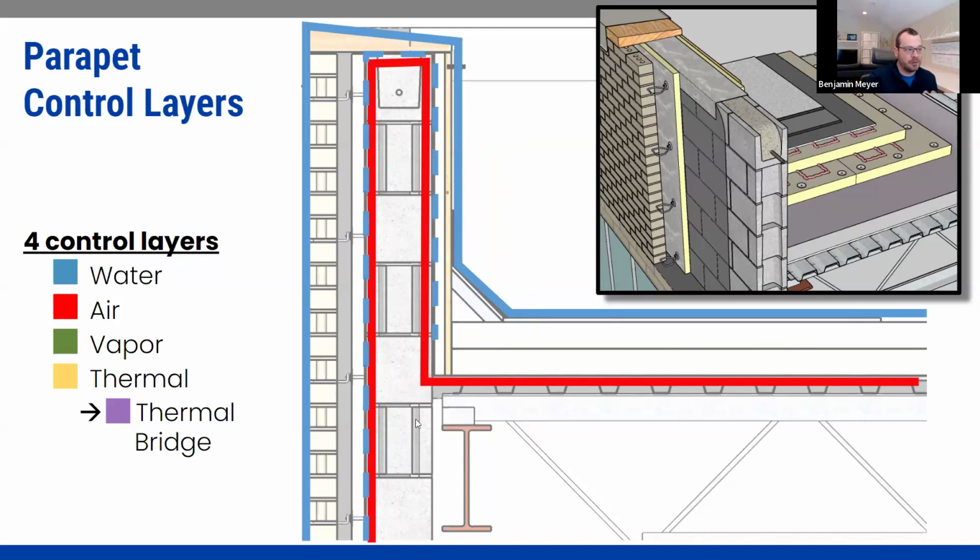When we have essentially a CMU wall and the air barrier is not continuous, what do we do? Part of the challenge is getting back into it if they're solid cores versus not solid cores. Creating continuity in that scenario on the inside might be your best approach, but it's a tricky scenario if you don't get it right the first time, especially with a construction type like this. And it's made even more tricky by how many trades are having to work together and integrate everything. Yeah, it's tricky.